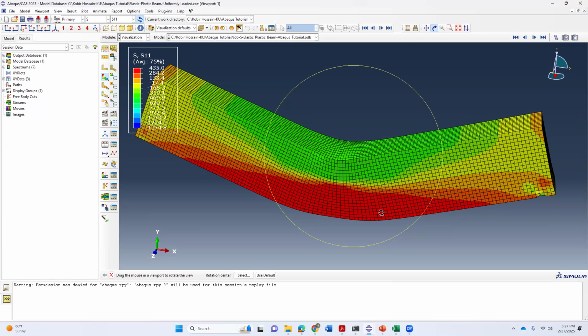But for concrete, definitely this mass deflection will not occur. Without any reinforcement, it will just break into two pieces. I will show that in a lecture. But if we reinforce it with, say, longitudinal steel rebar and shear rebar, we will have some resistance like this. But the concrete in tension will crack, and at some point, if you overstress the concrete in compression, it will crush too. So we'll cover those parts as well. But for now, just see the behavior of steel material.